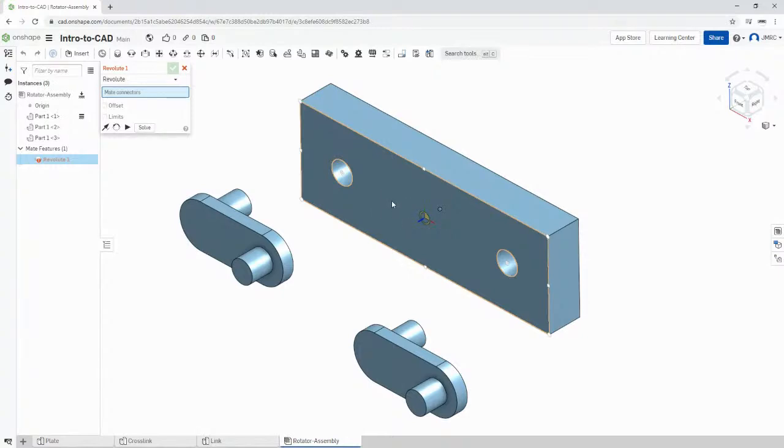Once more, notice this disc shape. This is called the mate connector. Now, as I move my cursor, it snaps to these points: to this circle, the white circle at this corner, to this midpoint, to this corner. So take note of that.